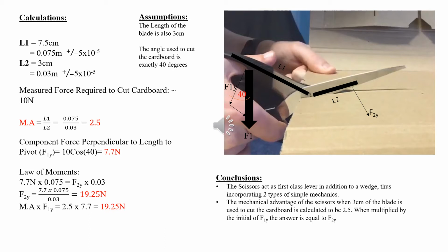We concluded that this type of lever has the greatest variation in mechanical advantage ratios compared to the second and third class. Also, that the force required to cut the cardboard would increase as the cutting surface moved further from the pivot due to the mechanical advantage decreasing.